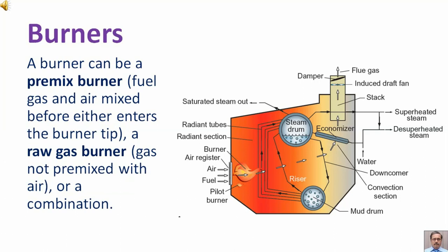A burner can be a pre-mix burner, that is, fuel gas and air mixed before either enters the burner tip, a raw gas burner, gas not pre-mixed with air, or a combination.